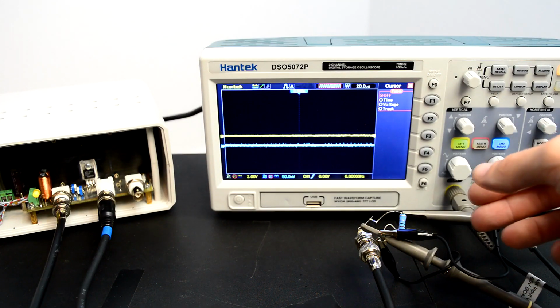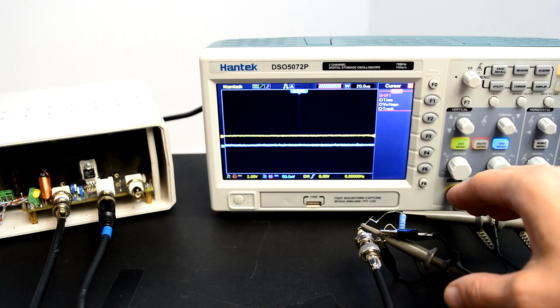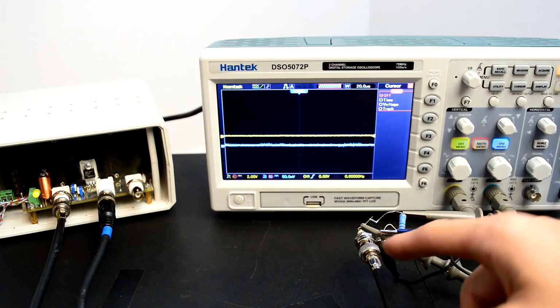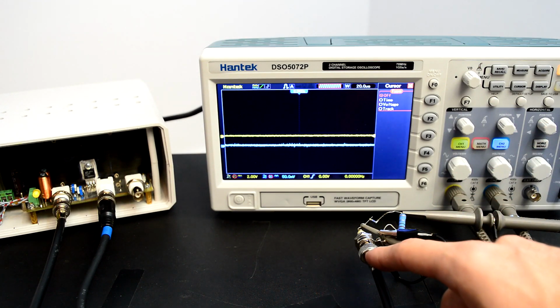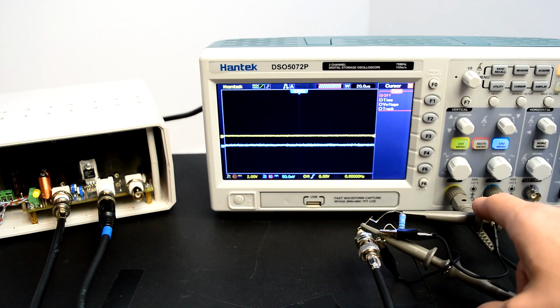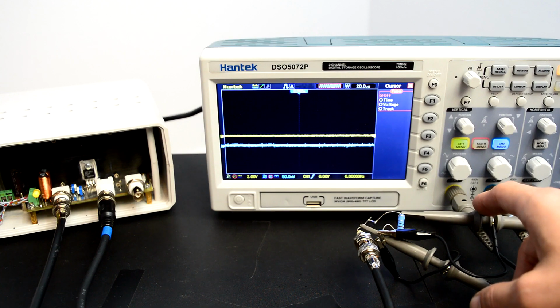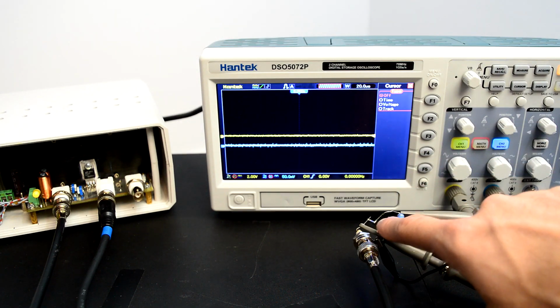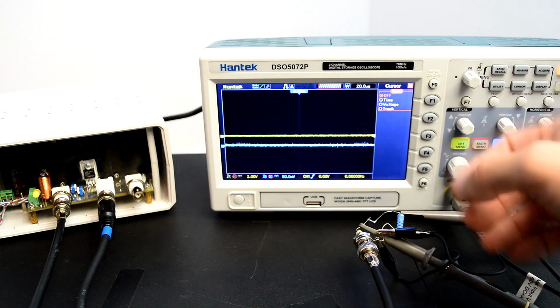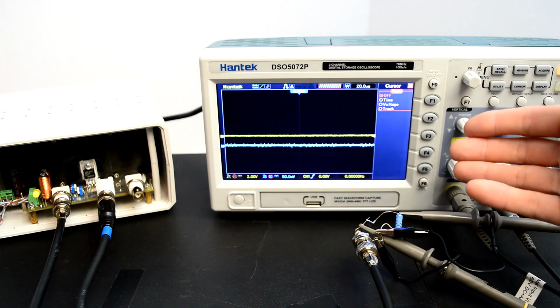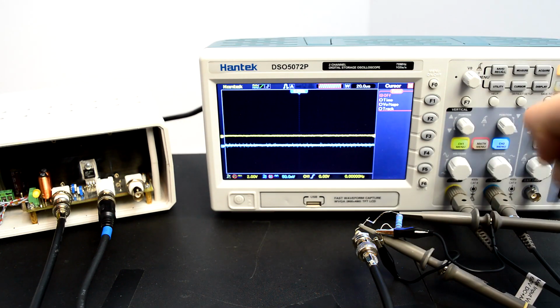So to test this behavior out, I got a similar setup to my first experiment. So basically, I'll be injecting the signal coming from the amplifier through a 1 ohm resistor, on which I'm also measuring the signal level, just to know what's the current going through the circuit, and then I'm passing it through this tiny little 680 microhenry inductor. So let's see what happens when we apply a square wave to this little circuit.